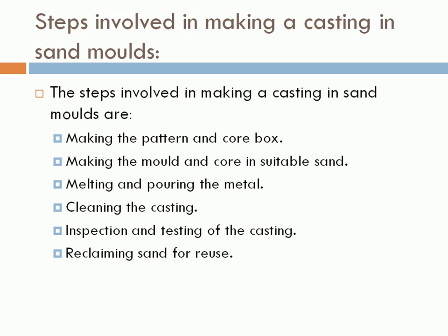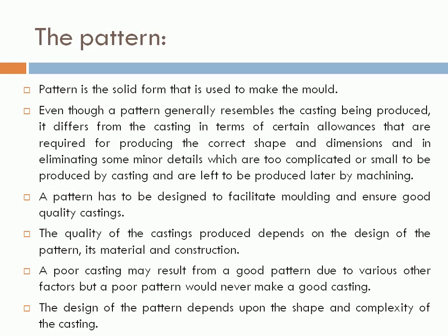After that, you have to clean the casting. After that, inspection and testing of the casting. And after that, the final one, that is reclaiming sand, if you want to reuse it for mass production. These are the different steps you have to follow to make castings in sand molds, right?